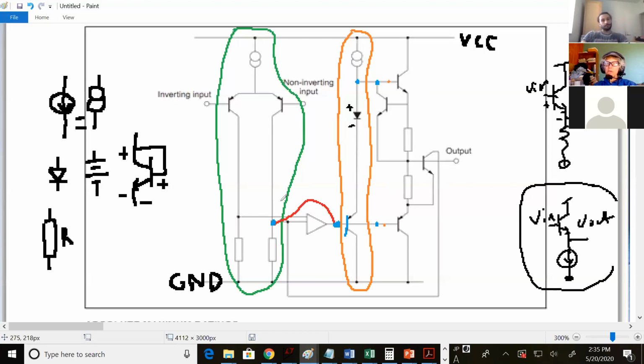Or it could be because when they directly connected this output stage to the diff pair, the output stage was loading the diff pair. So does that mean that it needed more current? It means that this stage was pulling so much current, it was messing up the diff pair. Okay. And so because we have a large RN for the common collector, that's not an issue anymore? Yes. Okay. Thank you.